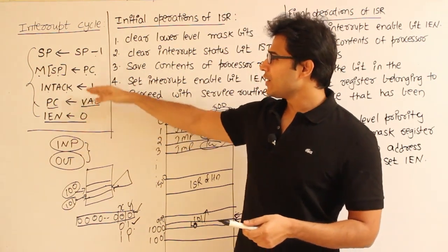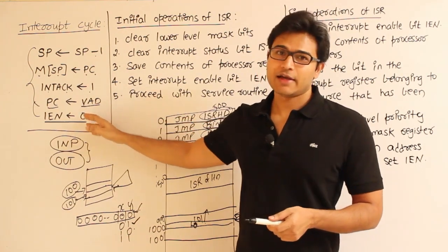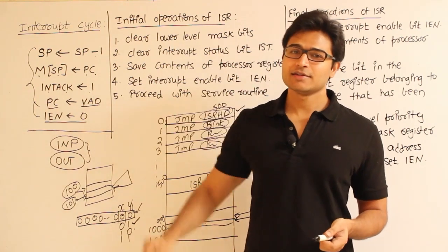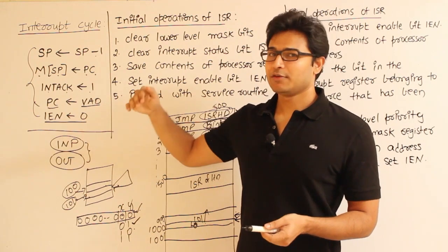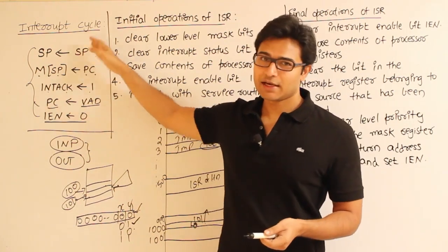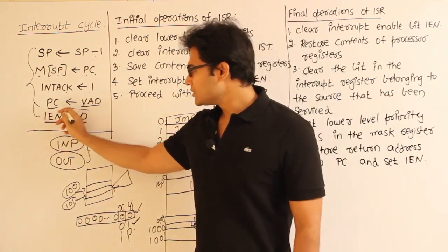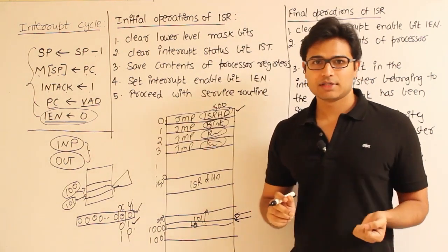Let us say you have just finished the interrupt cycle and you again got T0, and by that time if some other device again raises the interrupt, then instead of crossing this particular interrupt completely, we'll again get into the interrupt cycle, and it will be ambiguous. So the last step is you disable the interrupt for some time, and again we'll enable it. Okay, understood till this point?